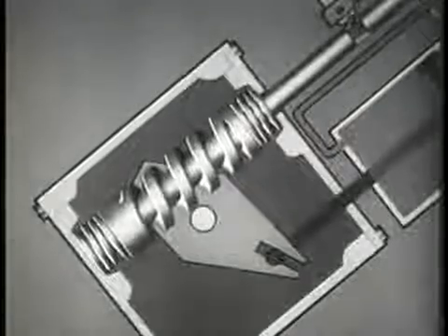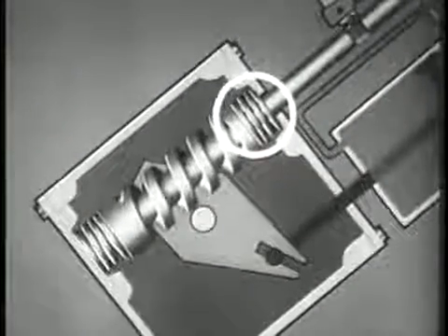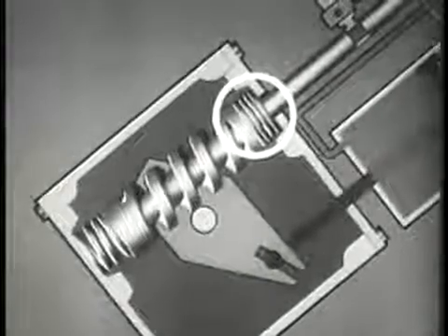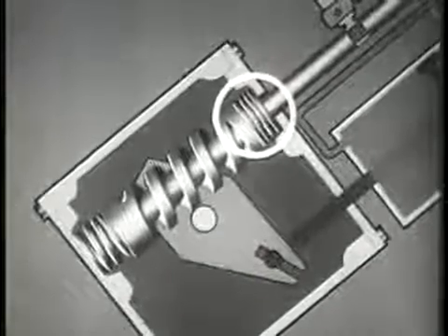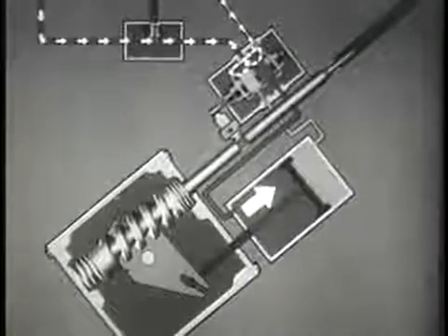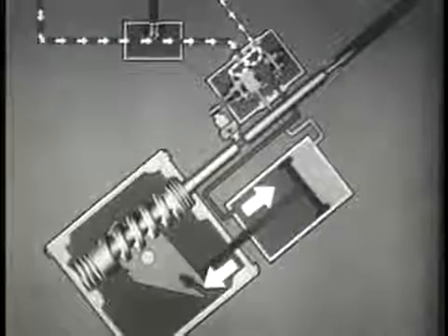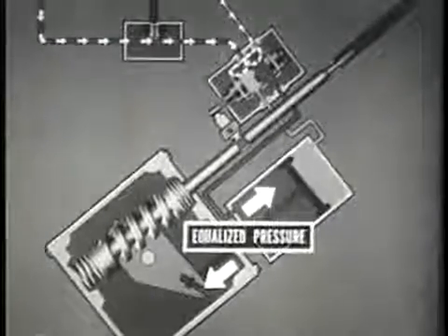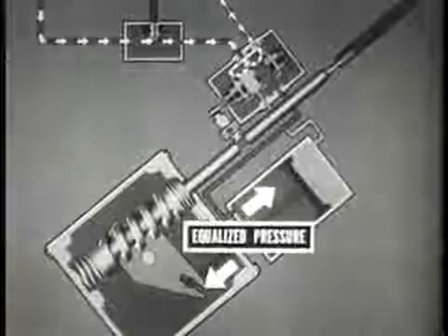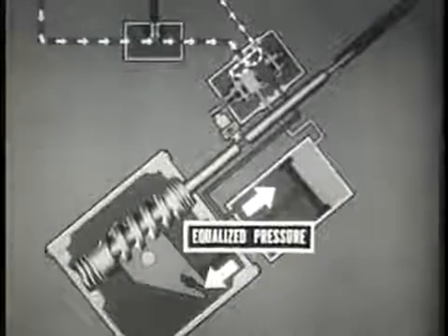These two opposing forces cause the steering cam to partially compress the upper cam spring. This also moves the control valve linkage and positions a valve spool where fluid pressure will equalize the force exerted by the steering geometry acting on the piston rod. The front wheels can then be held in any desired degree of turn.